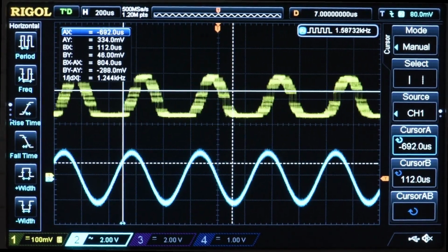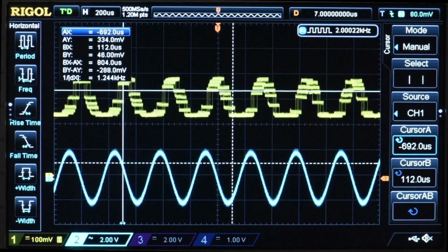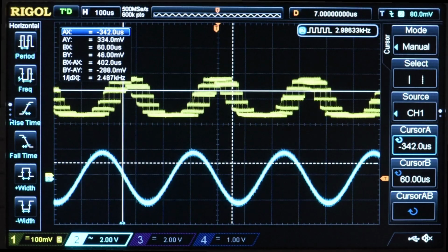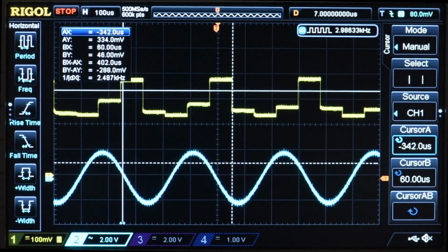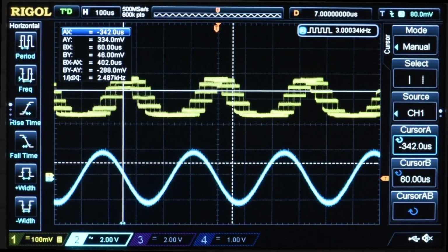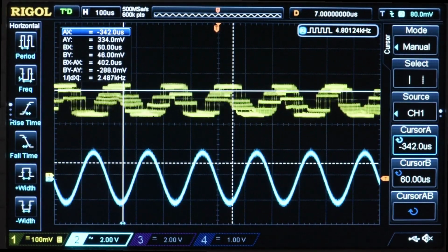I get the 16 sample average ADC value at a 12 kHz rate, and I just send that value to the DAC. So it's going to be a pretty rough looking waveform. Really, I just want to see if there is any output when the input frequency goes above 12 kHz. The top yellow trace is the DAC buffered output. The bottom blue trace is the signal input to the circuit.